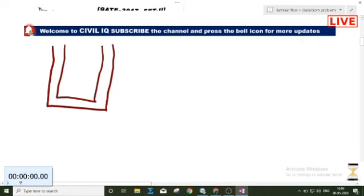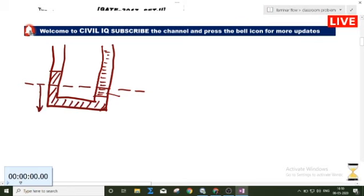So what will happen? This was the initial level of the mercury. There is a fall in the mercury on one side and this much gain of mercury on the other, and in the depression the water will come up to this height. This is the mercury level, and this height was given to you as 20 centimeter. So we have to find out this height h1, and this is my new height. We have to find out this new height.